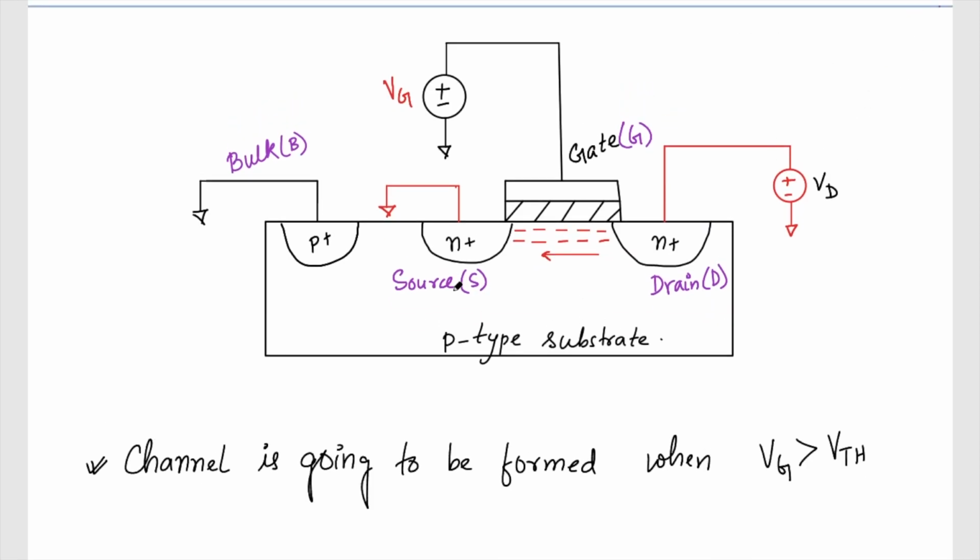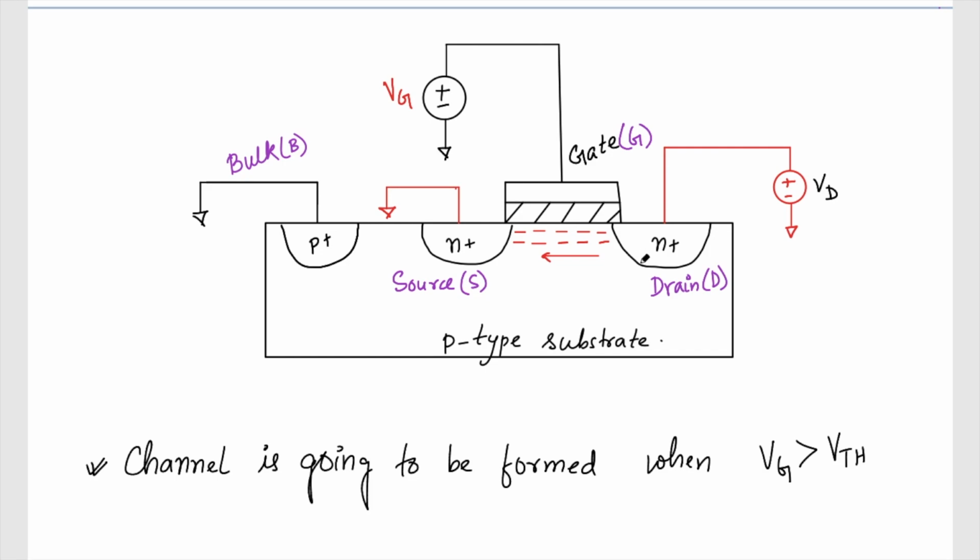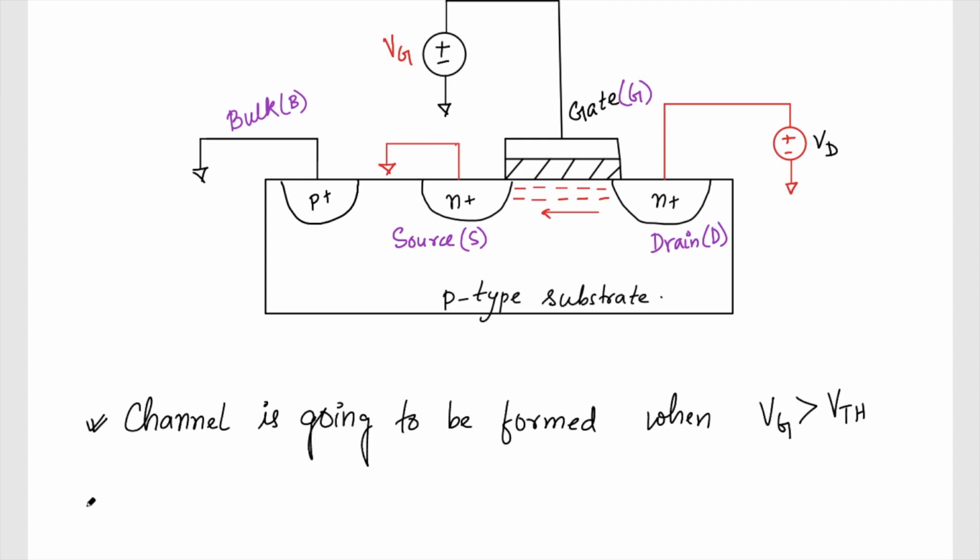So now if you compare to the BJT, the MOSFET has four terminals now: my gate, source, and drain. And of course I have this bulk, right? And the bulk is also important, because I'm supposed to connect this one to the lowest potential. Okay, so let's summarize what we have discussed.